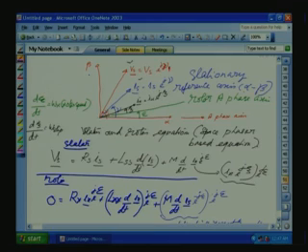Now when the machine is excited with sinusoidal currents or sinusoidal voltages in the stator, the stator will have ABC currents, so it will have an equivalent current space phasor Is. Now let us say the voltage space phasor Vs is defined as Vs underscore, voltage space phasor. It has a magnitude and angle. The angle we are referring with respect to the alpha axis, which is placed along the A phase axis.